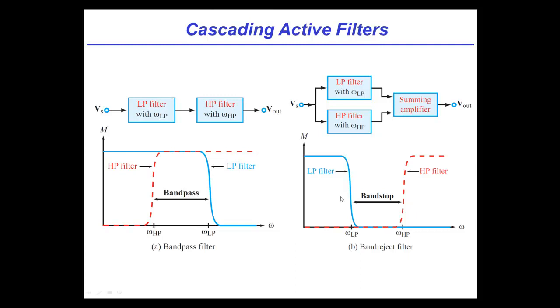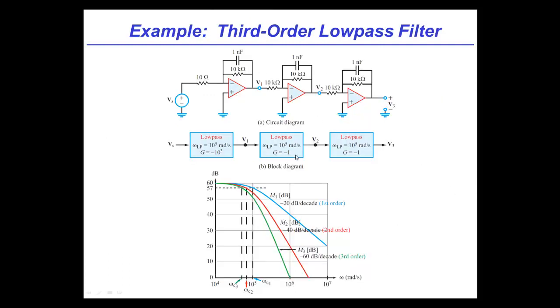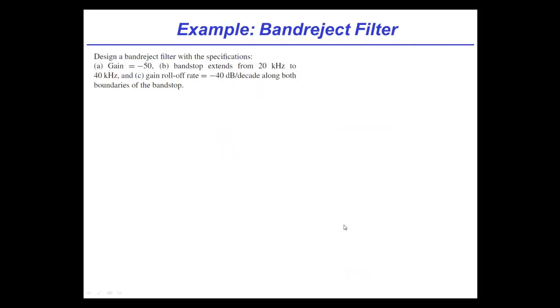And if we go forward, this is what you meant by 40 dB drop, right? Basically the steepness of this. Yeah, we need it to be 40 dB. And if you go to the next slide, here you see how we get the 40 dB. We take 2 first order filters, which just look like this, which have a single capacitive element, and we put them in series. Okay, let's move forward.